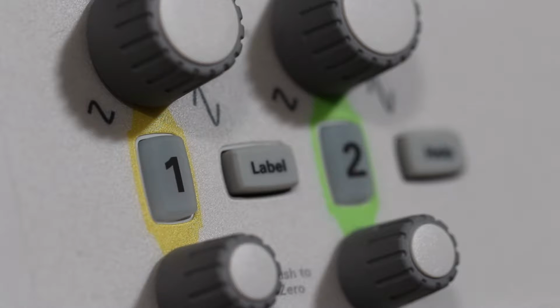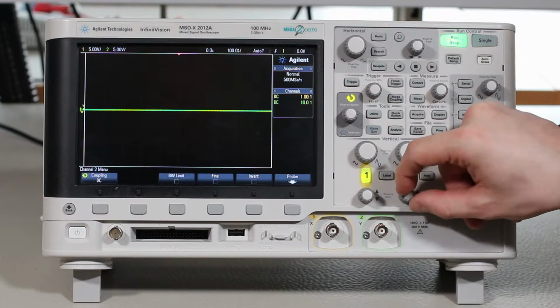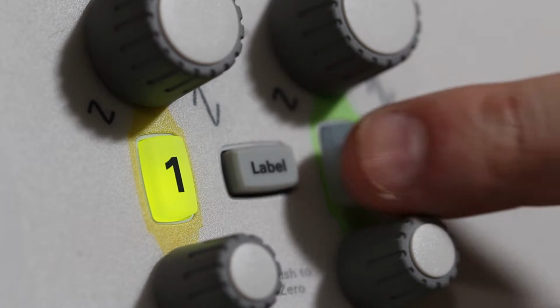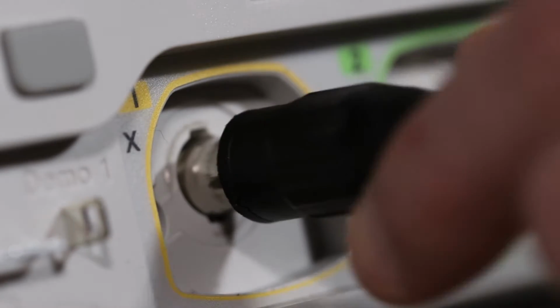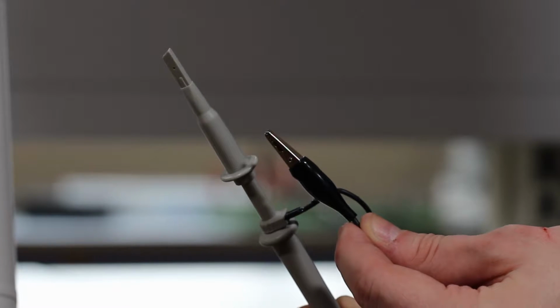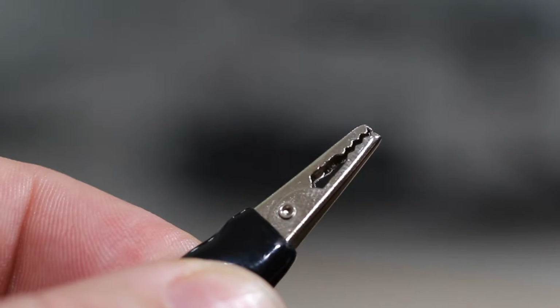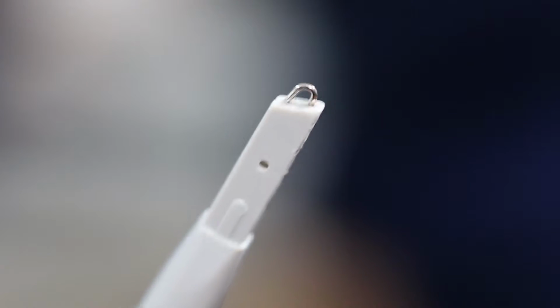Oscilloscopes typically have 2 or more channels. Each channel is used to look at a different signal. The function and submenus for each channel are selected by pressing the number button below the vertical adjustment dials. Each channel has a BNC (Bayonet Neill-Concelman) connector for a probe to be attached. The oscilloscope probe has 3 components: the main BNC connector, a crocodile clip reference connector which attaches to the 0 volts of the system being tested, and the probe itself, which is used to examine the signal at different nodes in the circuit.